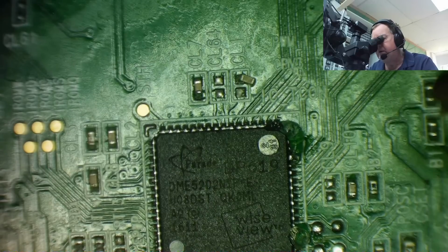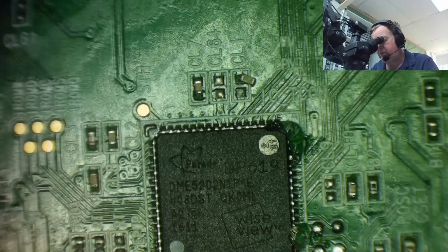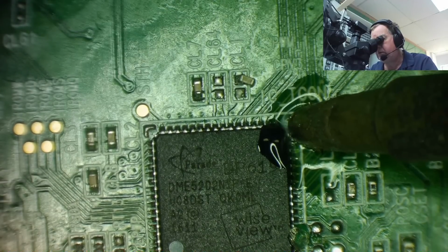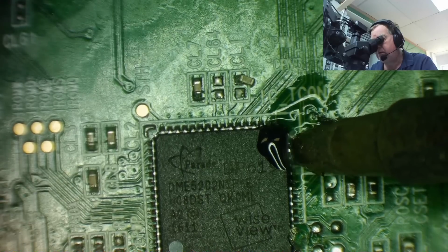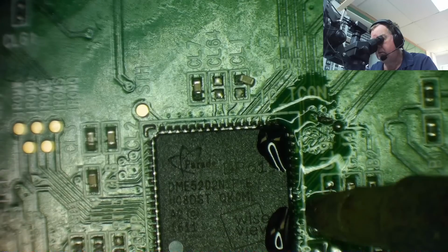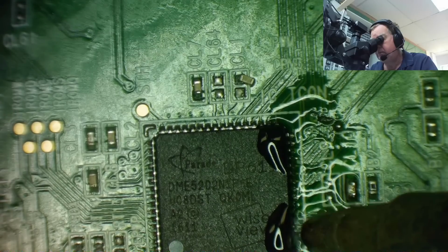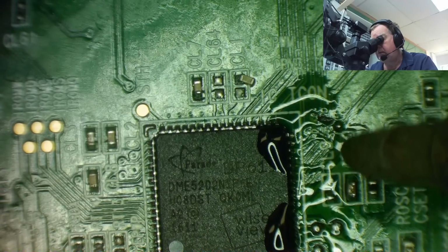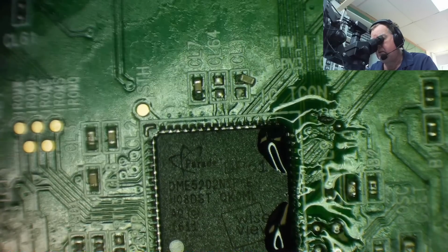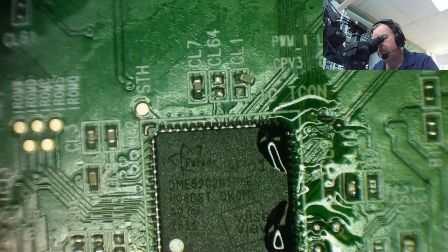I'll try first just coming in with the soldering iron and just seeing if that will effectively disappear, with a clean soldering iron, no solder. Yeah, looks like I've got that one. Let's get down on this as well. That looks like I've got that one as well. In fact, well, let's just touch down this side. Yeah, that looks good. This side, I'm thinking. No, there's one there, and then one at the end by the looks of it.